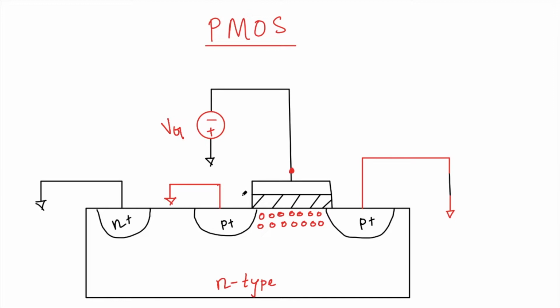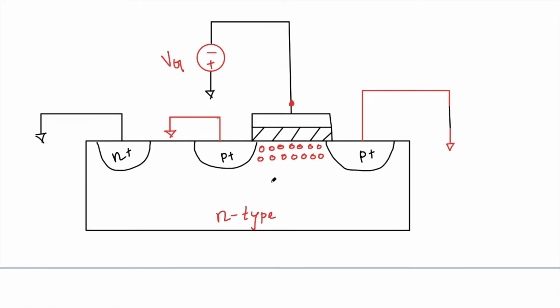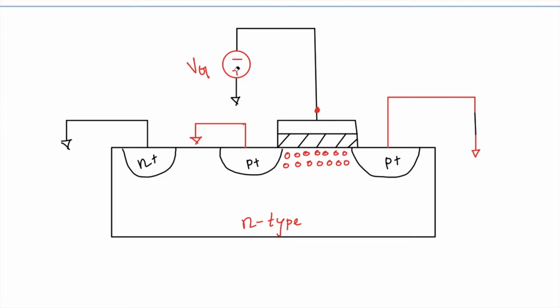into positive. So ultimately what matters is from here to here it should be negative. The VGS should be negative. And this is done something like this. So instead of applying a negative potential here, I will be applying a positive potential VG, but then I will connect all this one to VDD. Even the bulk also I'll connect to VDD, and maybe this to VDD. Okay.